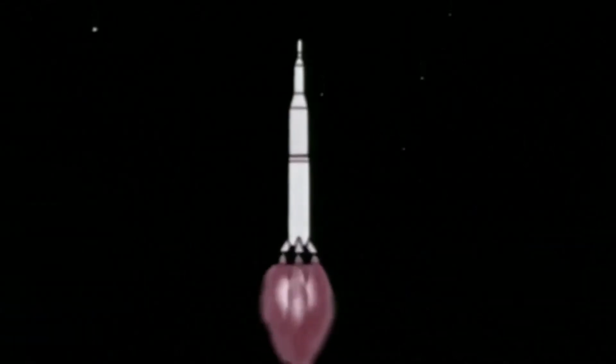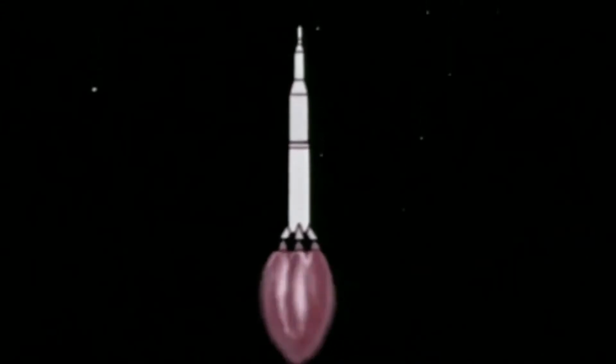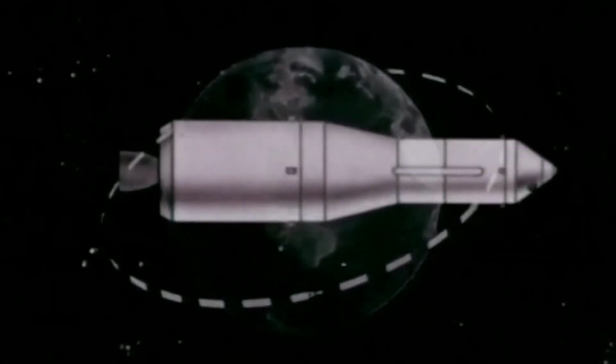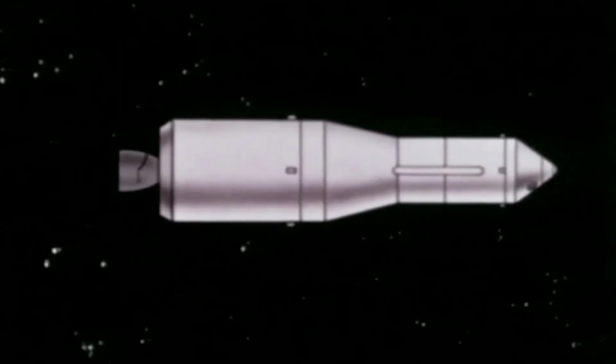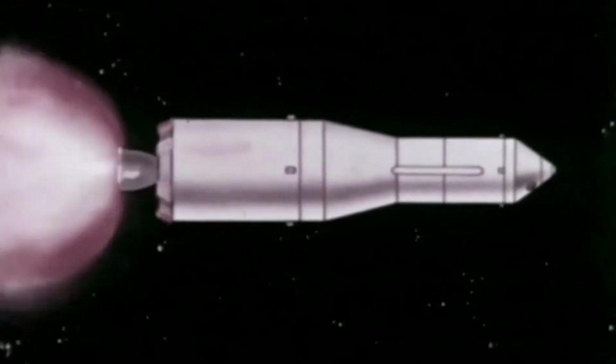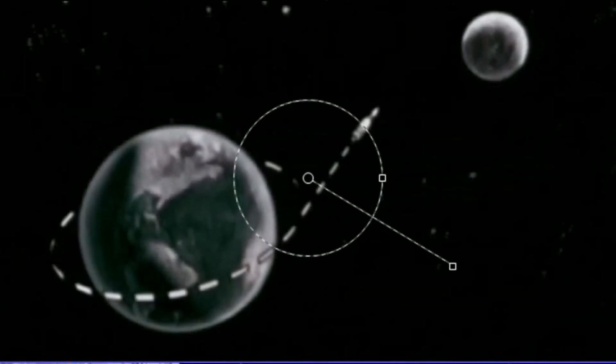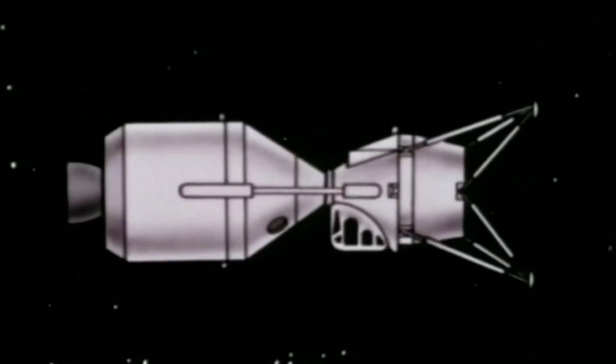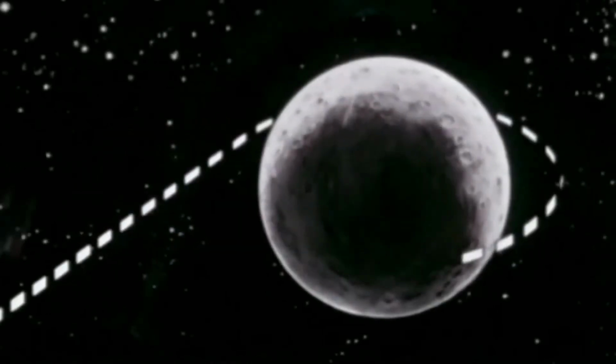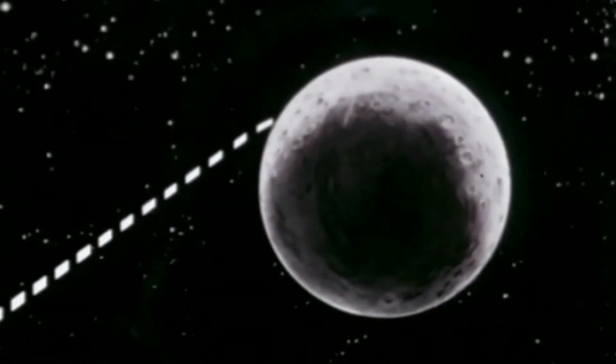One of the many important procedures for the Apollo spacecraft in maintaining a programmed route to the Moon was to fire the engine of the S-IVB for a limited time for translunar insertion, TLI. This is done to put the spacecraft on a proper trajectory to the Moon. If engine thrust was precise, it would put the CSM on its proper trajectory, that is, an elliptical orbit around the Earth extending to the far side of the Moon. This is the free-return trajectory, which would have put the Apollo spacecraft on a course around the Moon and back to the Earth in the case of a service module engine failure.